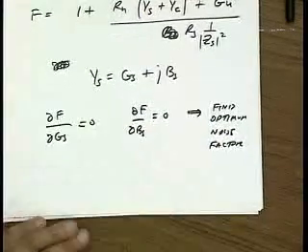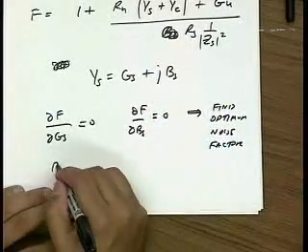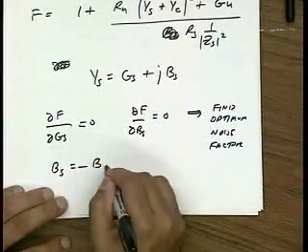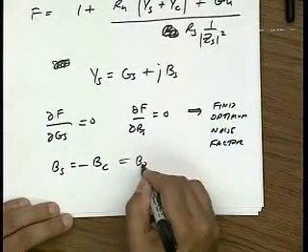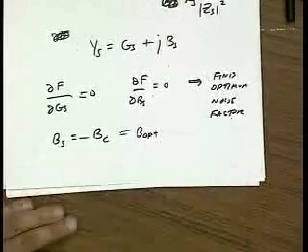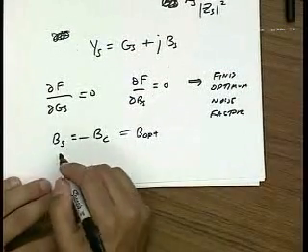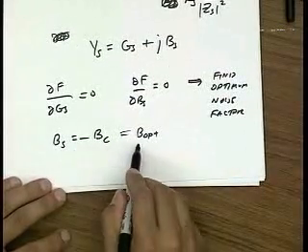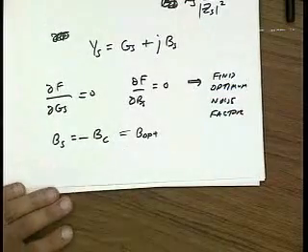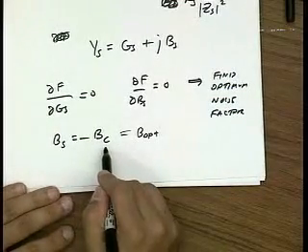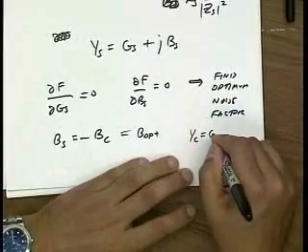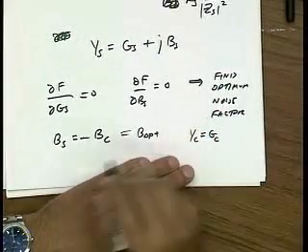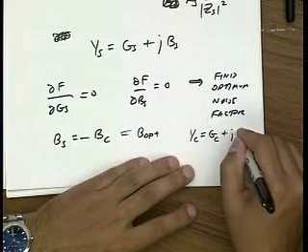Okay, and what you find when you do that calculation is that the optimum value of the source admittance, the imaginary part, is simply the complex conjugate, basically minus Bc, where Bc is the imaginary part of the correlation coefficient. So we could write the correlation coefficient as Gc plus jBc.